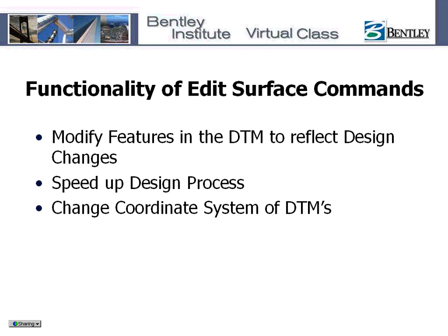The other function of these commands is that you can change coordinate systems of a DTM. You can change the vertical datum from an arbitrary datum to a new vertical control midstream through a project. You also could translate a surface from English to metric units or vice versa. And you could also do a variety of other custom transformations.